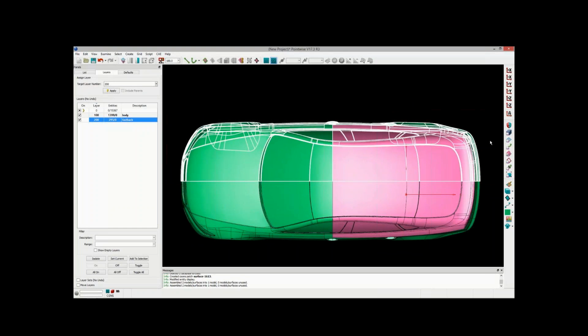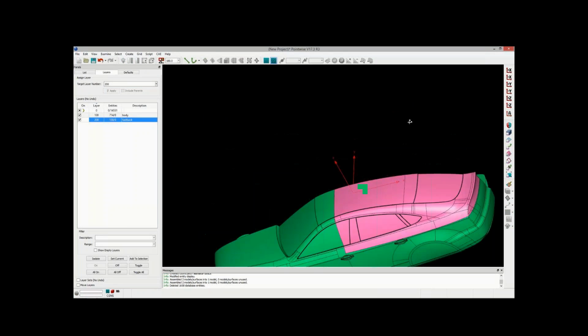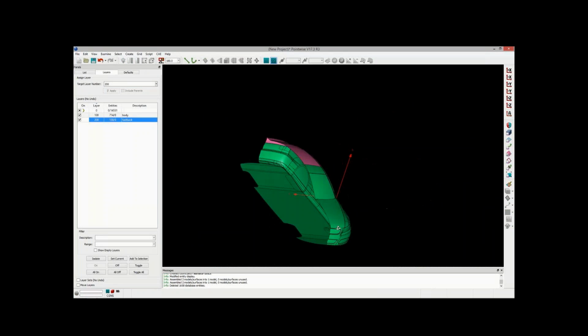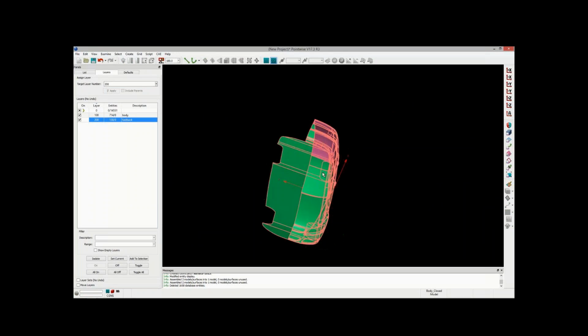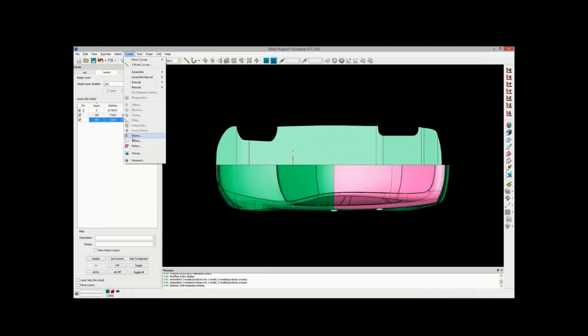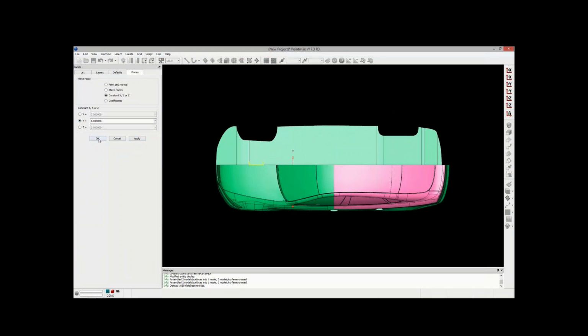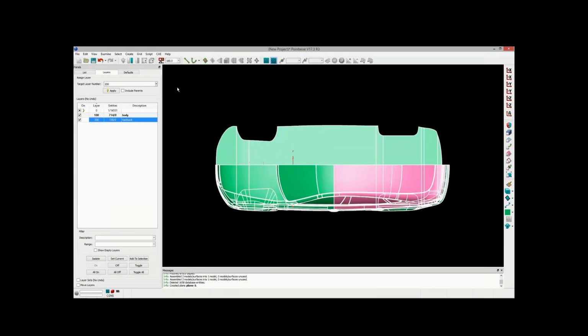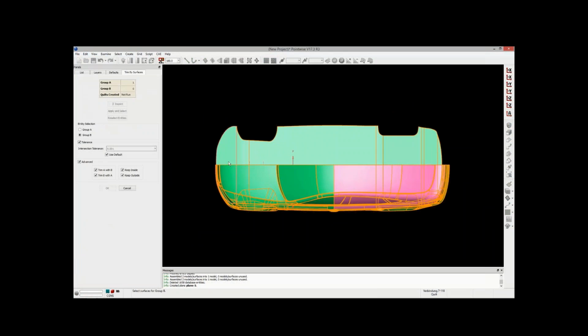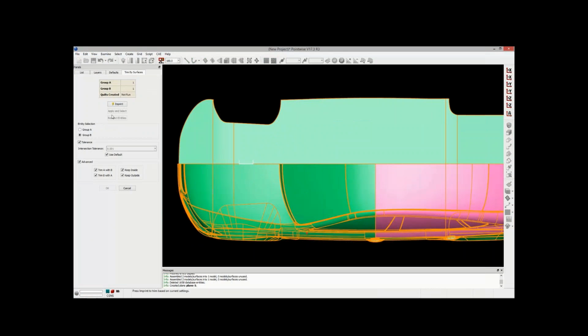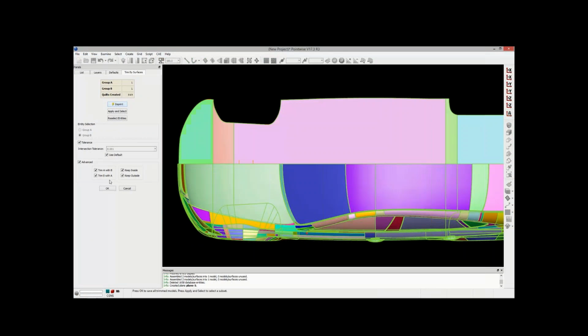Now what I'm going to do is I'm actually going to poke a hole in it. I'm going to cut the thing in half. Okay, so why work on the whole thing if I'm just going to end up cutting it in half? Well, by creating a model for the entire geometry, I know that there should be 0 lamina boundaries. If I had just created a model for half of it, there would be a collection of lamina boundaries at that symmetry because that's where there's a hole.